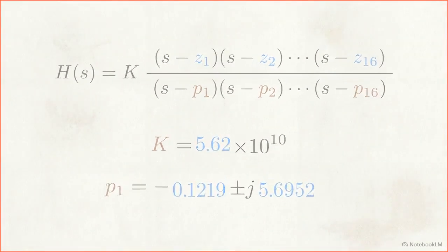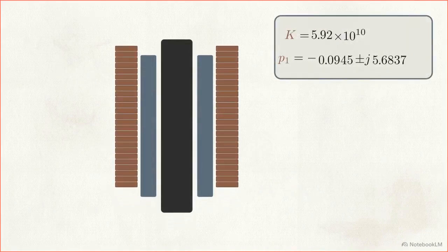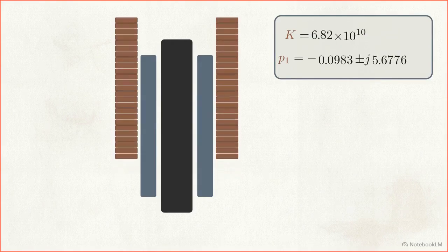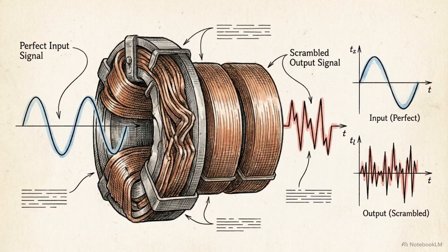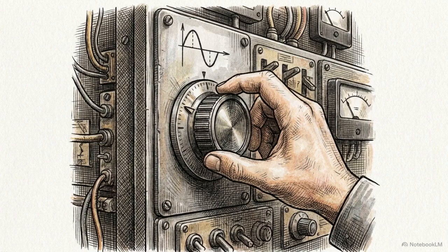We can stress test this shifting model across 4 distinct fault conditions, simulating axial displacements of 15, 30, 45, and 60 millimeters. The resulting mathematical models tell us exactly how the damaged transformer will alter injected signals. That gives us the raw data needed to test both time and frequency domain metrics for reliability. We evaluate the frequency domain first, as it is the most common diagnostic testing ground for linear systems.